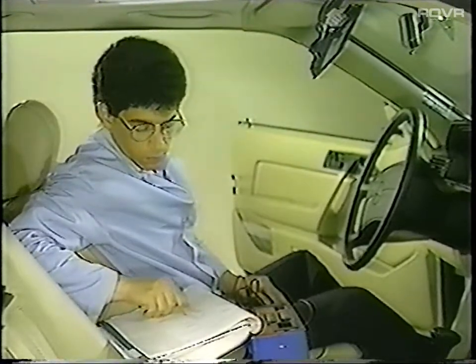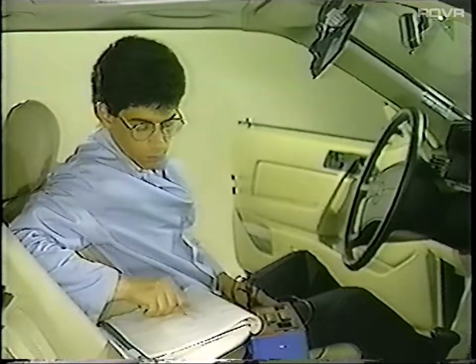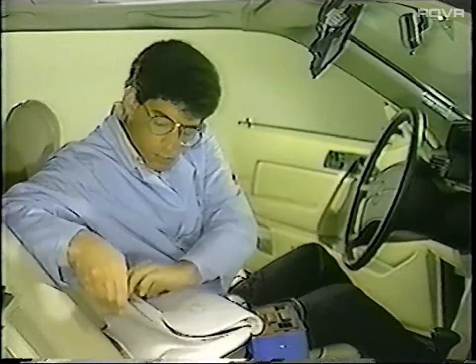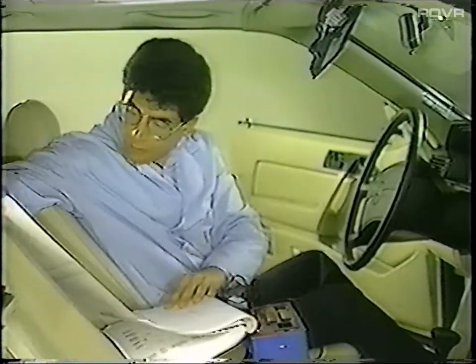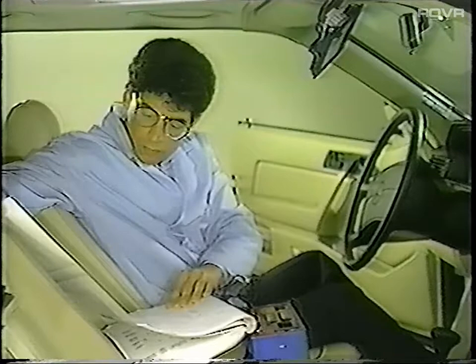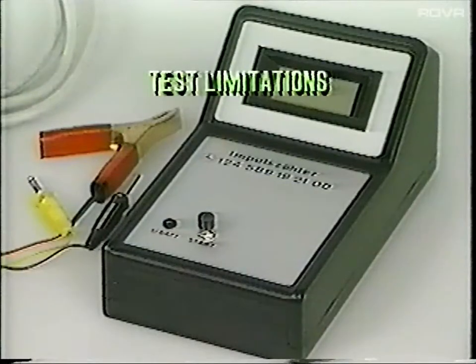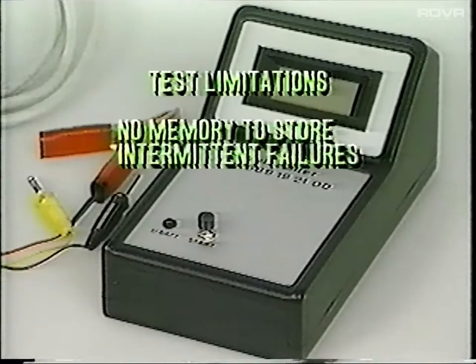You will find that all test programs included in the 1988 Introduction Manual are arranged in this new format. Incidentally, a wiring diagram is included at the end of each test program for quick reference. There are a few additional important points which must be emphasized. First, the impulse readout for the climate control systems will only indicate a malfunction which is present at the time the test is being performed. It does not record intermittent problems as there is no memory feature.